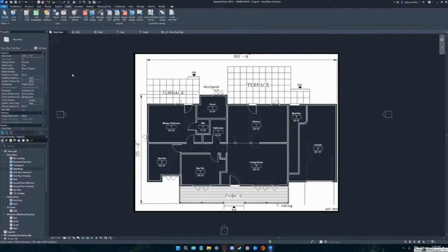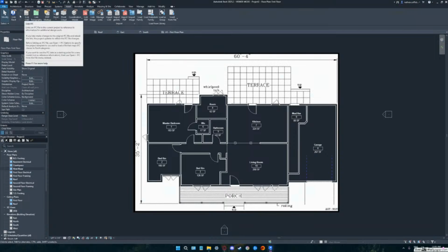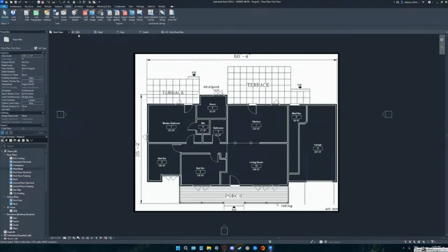We'll get deeper into that, but that's typically how I set up a building. The site work, I don't typically do that in there with the architecture, because you don't add that topography till later, and then you mess up all your views by putting that in there. So what I want to explain to you is that Revit link we will use. The next one over is the link IFC, which I don't know why yours is grayed out. Is that because he's in a 2D? No. I don't know why they would do or clear it for that. It may just not have added that extension.